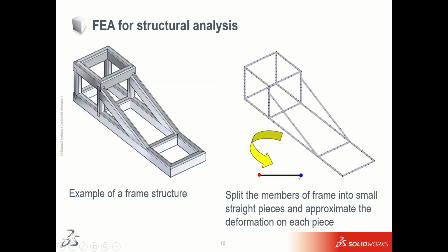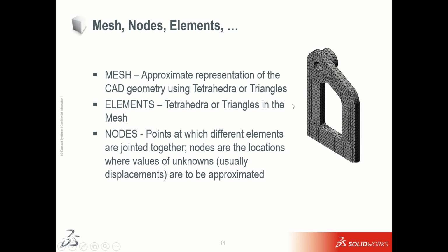And the last one is a 1D element, or you can say a beam element. Here it's only one linear line with 2 nodes, and it also contains 6 degrees of freedom, that is 3 translation, 3 rotational. And your beam structure or any weldment structure is automatically treated as a 1D element.